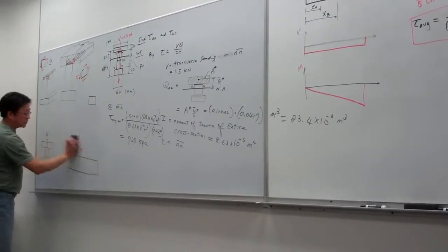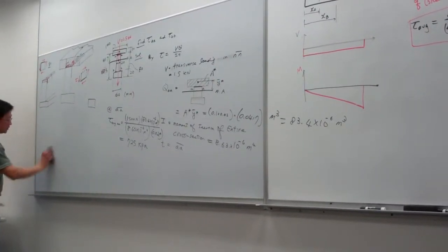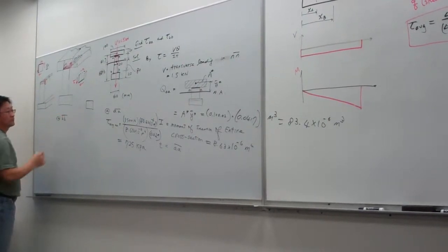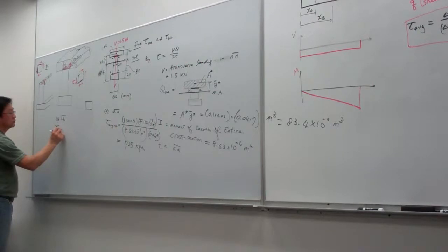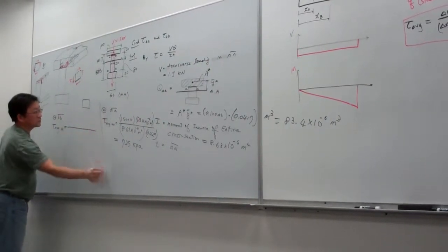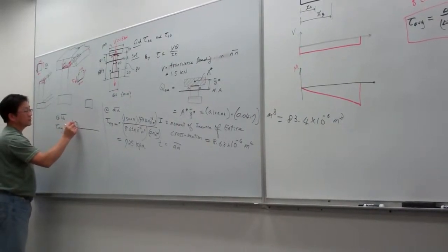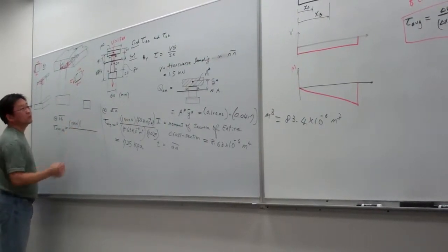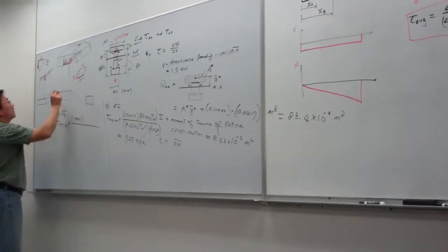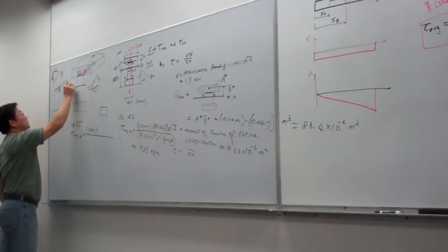So now we're back to continue to calculate B. So at B, the tau average along BB will be equal, with the same calculations, 150 newtons. Q will be, right now for the Q, this is our neutral axis.